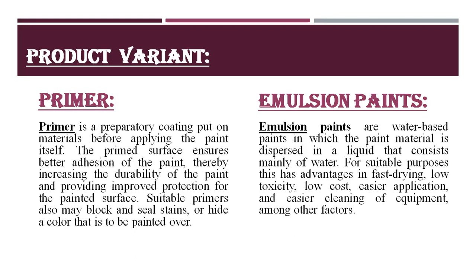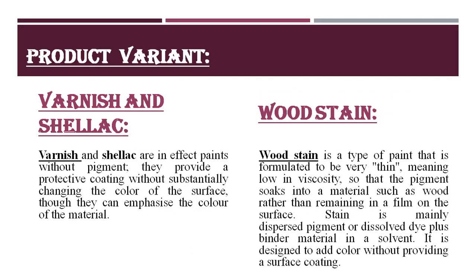Second is emulsion paints. Emulsion paints are water-based paints in which the paint material is dispersed in a liquid that consists mainly of water. For suitable purposes, this has advantages in fast drying, low toxicity, low cost, easier application, and easier cleaning of equipment among other factors.